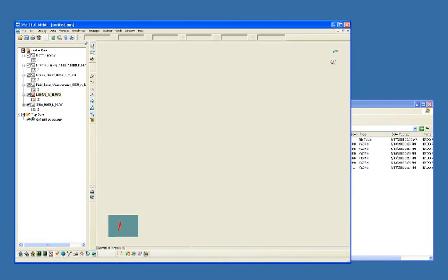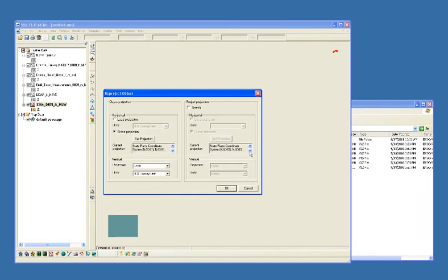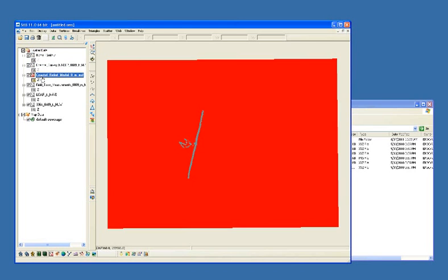So you have one more data set that we need to convert horizontally, and that's this one. So we do the same thing again. Reproject, global projection, state plane. We want to go from feet to meters. And now all of a sudden, everything shows up in the same screen. All right, and I'm just looking at the different individual ones.